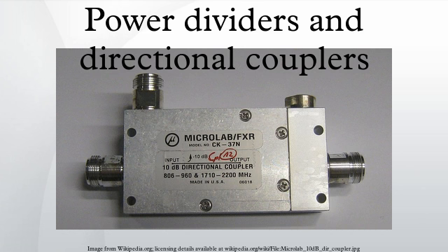Directional couplers and power dividers have many applications. These include providing a signal sample for measurement or monitoring, feedback, combining feeds to and from antennae, antenna beam forming, providing taps for cable distributed systems such as cable TV, and separating transmitted and received signals on telephone lines.